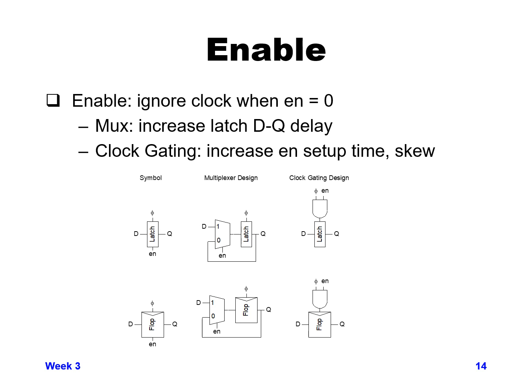Second type of design we can do is we can take an AND gate and have the clock go into an AND gate along with enable as the other input to the AND gate. So if the enable is 0, the output of the AND gate will always stay 0 and will never switch. So the latch will always stay closed, keep the same value even as clock is toggling.